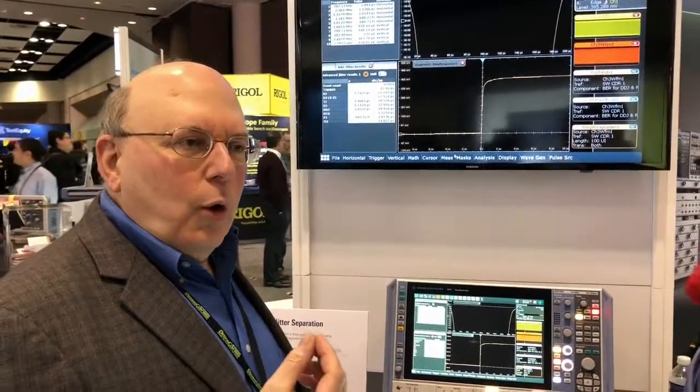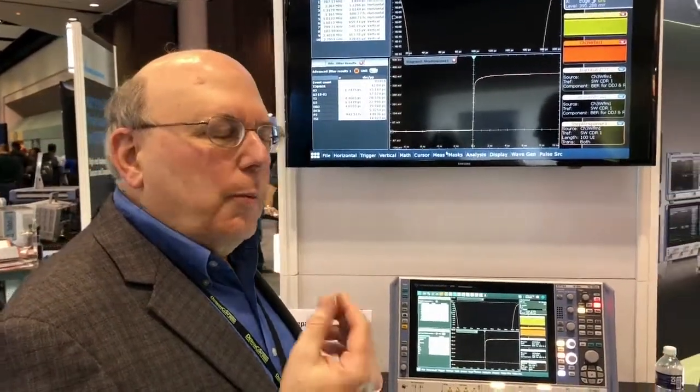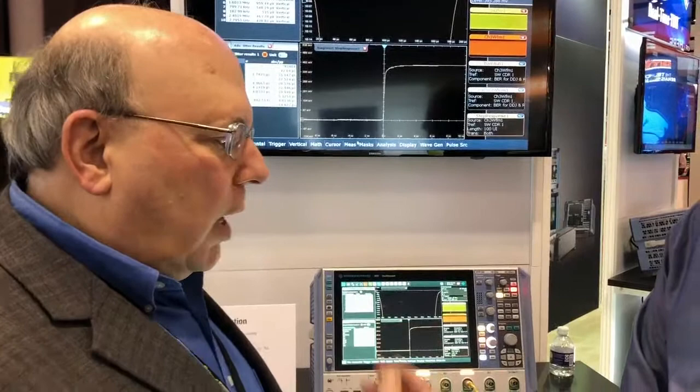Now, why do we care about jitter separation, or what is even jitter? Well, if you've got a stream of bits coming along down your channel, guess what? They don't all arrive at exactly the same time. There's a little bit of difference from one bit to the next, or from one group of bits to the next, and we need to know why that happens. There are many different reasons for different forms of jitter. Mike's going to tell us why. How do you find those different forms of jitter?